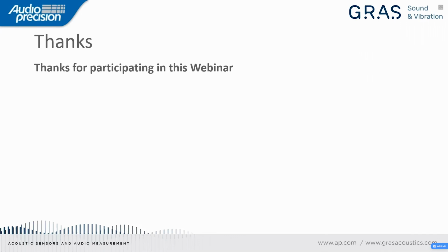So the 94 dB is what we have been doing in the past, according to IEC 60268, while the 89 dB for the microphones is due to the fact that we are not speaking that loud normally.